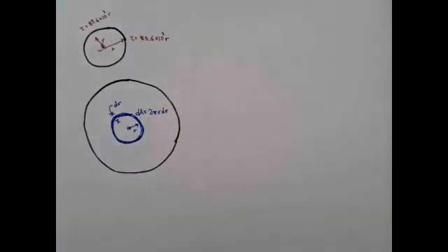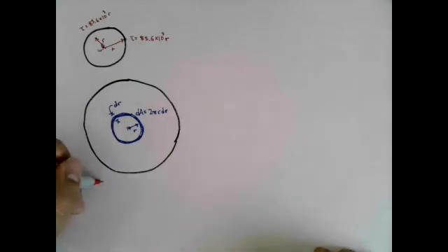So why am I doing this? I'm not really doing this because I want to go back to calculus. I'm doing this because it is the only way for us to calculate a full torque for this element. So if our goal is to find a full torque, let's first find the force that's acting on this differentially small element dA. In this element dA, there is a differential force called dF.